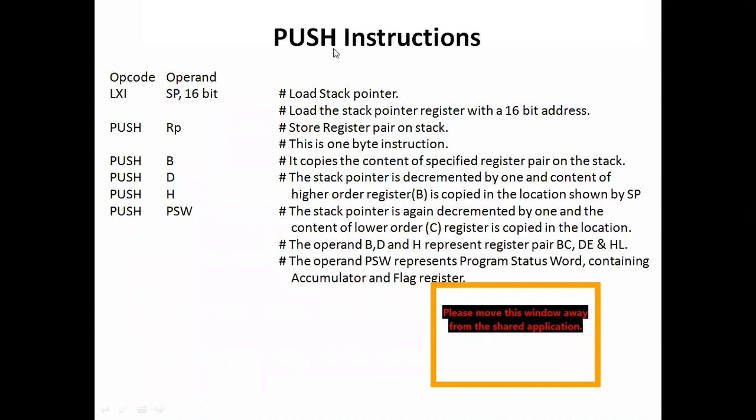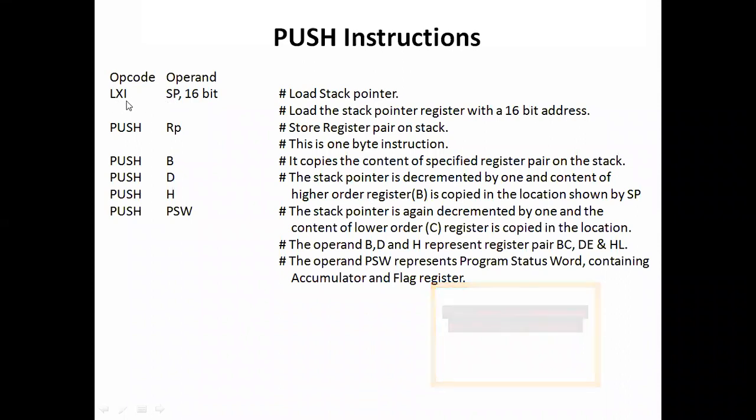So first of all, we will be discussing the push instruction. Before using the push instruction, it is necessary that we initialize the stack pointer. So what we'll be doing is using an instruction like LXI SP, 16-bit.